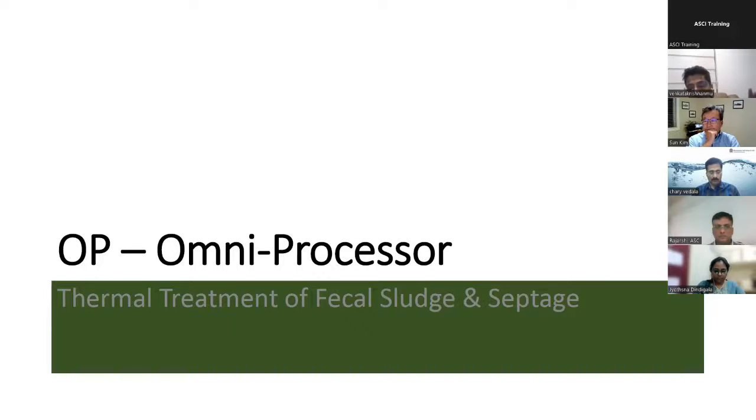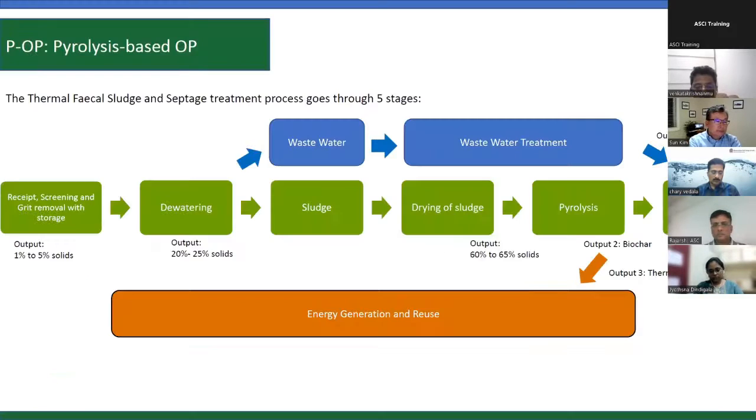But basically, they are separated by the physics. One is a pyrolysis-based design. The other is more of a combustion-based engine that helps deal with the fecal sludge. And it does all of it, which we discussed for the reinvented toilet, at a community level. Basically, it takes in septage and fecal sludge and converts it into germ-free, pathogen-free biosolids, and the water effluent can be treated to the quality we want it to be. We can take it as far as drinking water quality if you want to, and that has been demonstrated as well. So next slide, please.